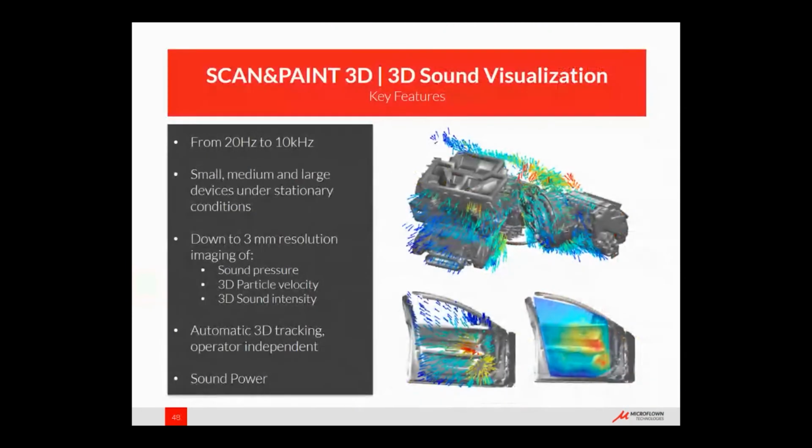It works in essence very similar, with some key features. We can measure the full range of small, medium, and large devices. We can get a high spatial resolution mapping, in this case down to 3 millimeters. We can visualize sound pressure, 3D particle velocity, and 3D sound intensity. We have automatic 3D tracking of the position. And also, based on the sound intensity data, we can calculate sound power.